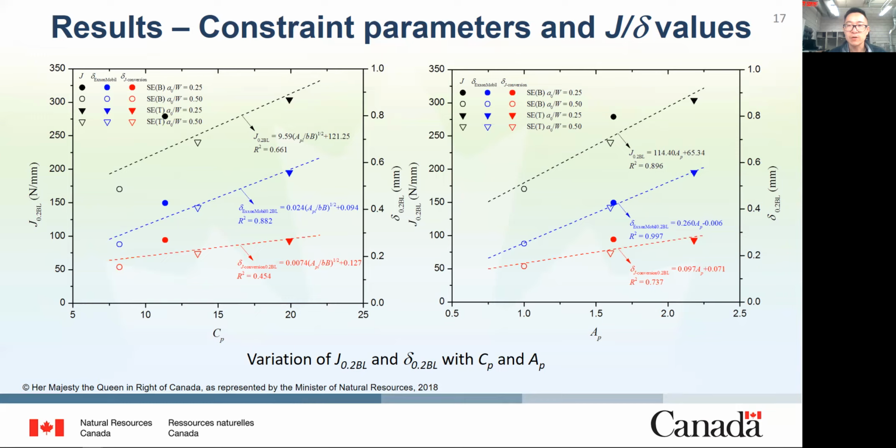It generally has a coefficient of determination R squared value greater than 0.9, except for critical J converted CTOD, with an R squared value of about 0.75. In terms of the stress-based constraint parameters, QHRR, QSSY, and H have more promising trends compared to others. In summary, AP works the best.